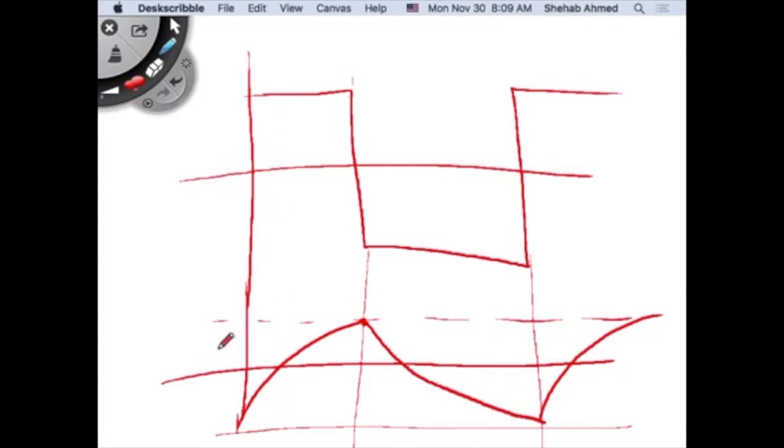Do these have the same harmonic content? No, they look quite different from each other. So then we said that we want to start working on how we optimize the harmonic content, because at the end of the day, if the voltage and current waveforms have similar harmonic content, then you can transfer real power. If they don't have similar harmonic content, then you have currents and voltages at different frequencies that do not contribute to real power transfer. So that's the final objective here.